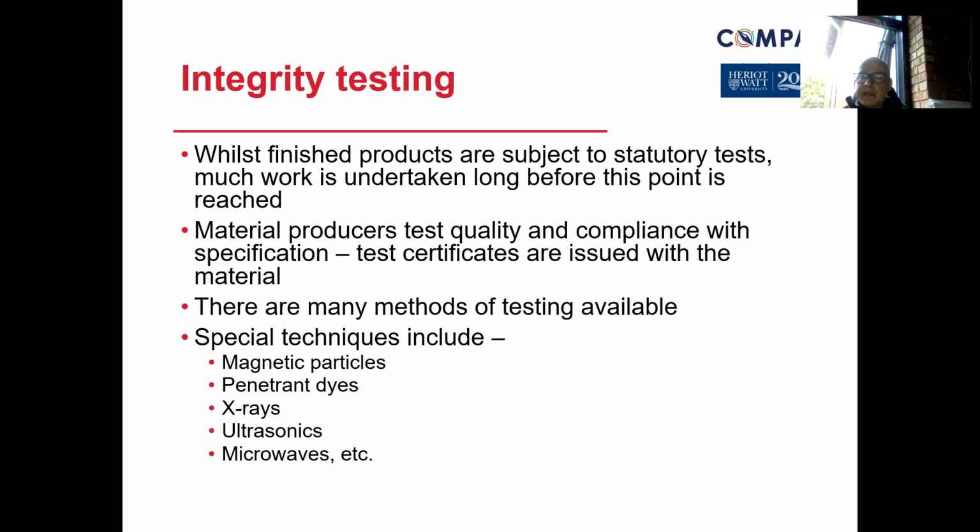They'll say, well, the safe working load of this, let's say, is 3 tons, so it can lift under 3 tons. Based on the safety factors, we'll put 3.5 tons on it. And if it is okay after that test, we'll sign it off. But if it then shows that the crack is opening up, we'll say, no, it needs replacing.